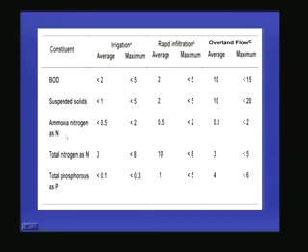In all the cases, ammonia nitrogen should be less than 2 milligrams per liter, and total nitrogen should be less than 5 to 8 milligrams per liter, and total phosphorus should be less than 0.3 milligrams per liter in case of irrigation, and for rapid infiltration should be less than 5 milligrams per liter, and for overland flow it should be less than 6 milligrams per liter.